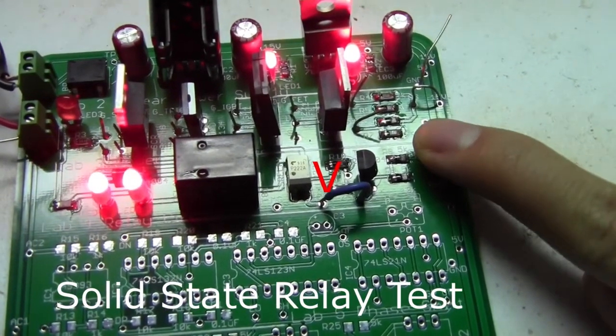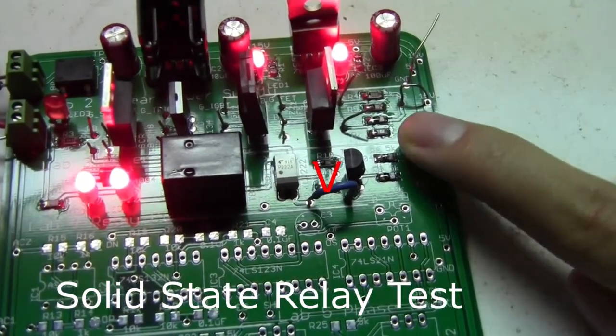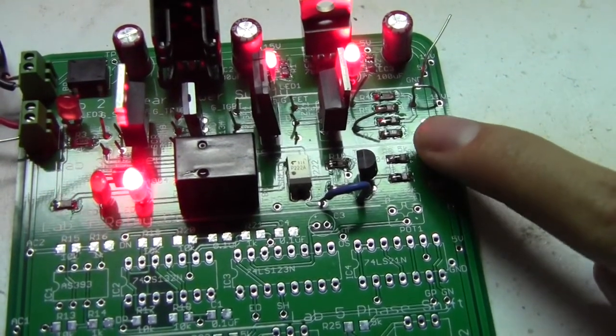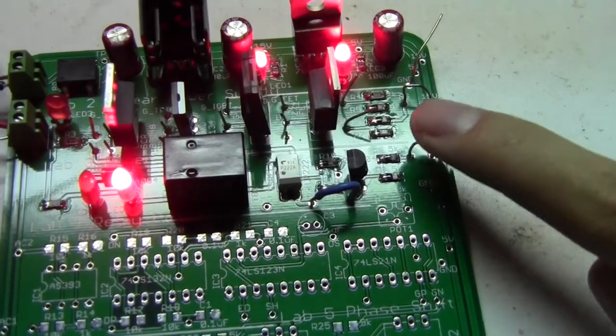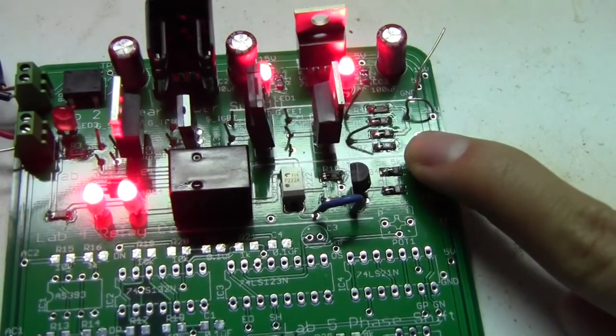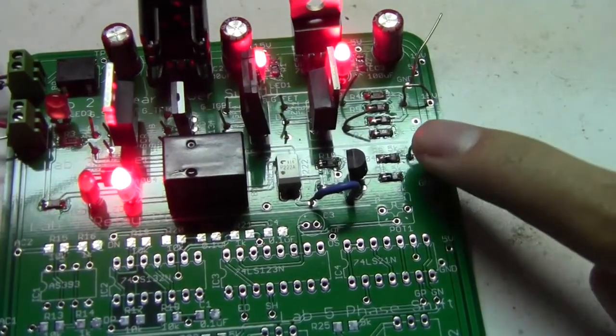To test the solid-state relay, the common control signal CC is connected to the internal LED terminal SC. We can see, when the control signal control is pushed down to connect to 5 volts, LED 4 turns on. When the control signal is off, LED 4 turns off. LED 5 remains on, since it is not in the power path of the solid-state relay.